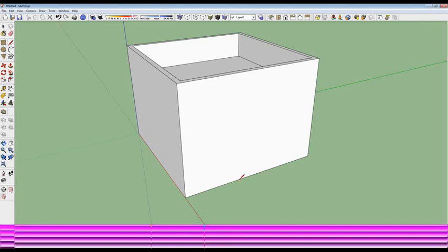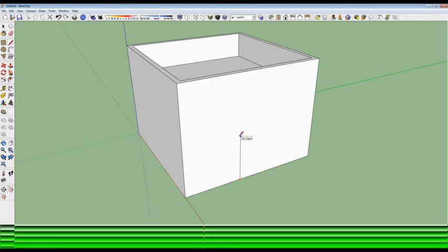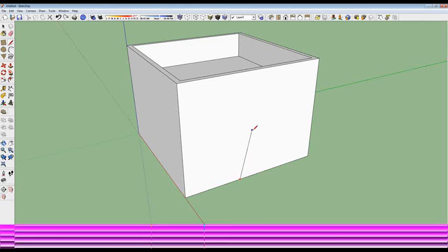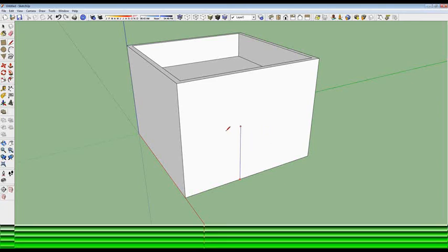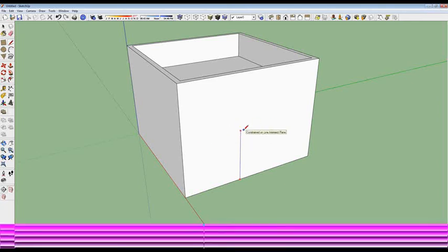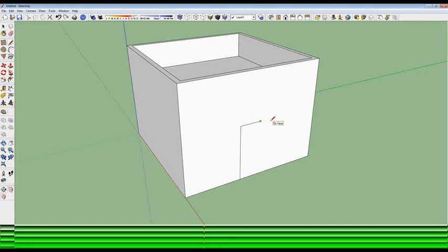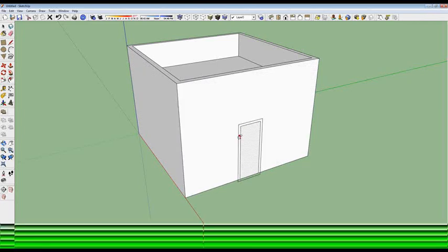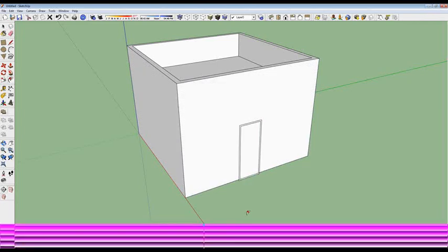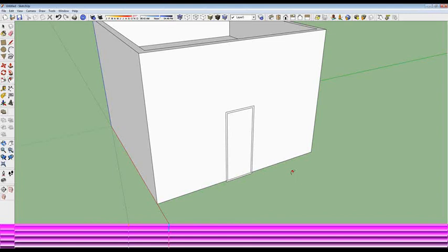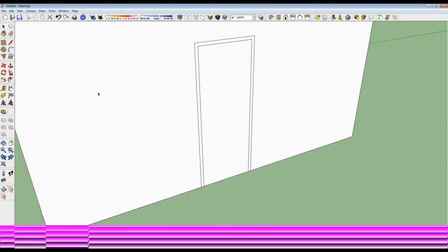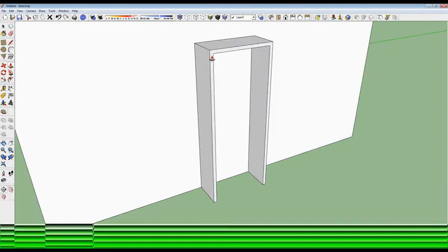And then it was kind of the same idea for the door. I just drew it up using the arrow keys again to force the direction that I would like to go. So if I hit up, I can't actually go in any other direction. I have an 8-foot by 3-foot door. Drop that in there, offset that. So very quick to get caught back up where we were. I can take out these base pieces and use that same push and pull tool to give it just an inch reveal.